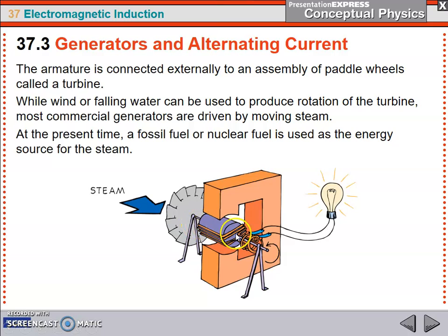Then that spinning fan we hook up to the generator, which is the coils of wire wrapped around the magnet, and then this rotates around like that. So these coils are going around and around, and those coils are what gets the voltage coming out over here. And this voltage is made because this big magnet is stationary, and it always has the north field going down, and that's the field lines that these are crossing. And that's the name for the part in there that spins, the armature.